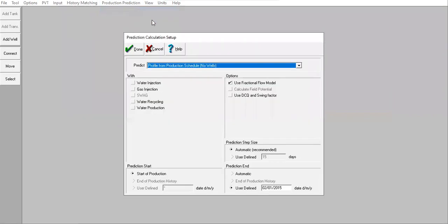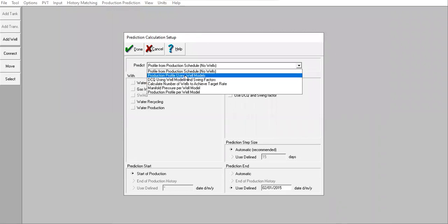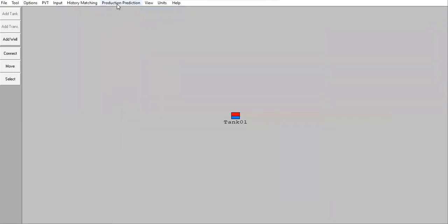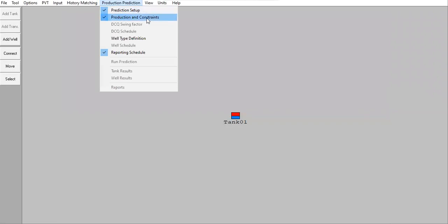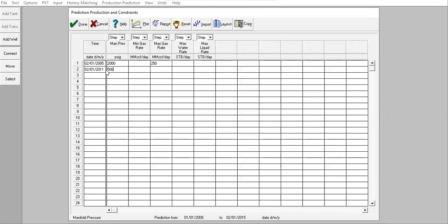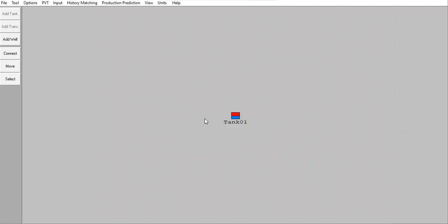So again, we will go back to production profile using well models. Okay, and we will have production constraints like the earlier, but the well will be constructed using Prosper, and then we will connect the well and the reservoir using GAP. Okay, we can actually connect the well using this software only. All right, this software alone can do that, but we want to connect it with network simulation. So better if we do integrated simulation.